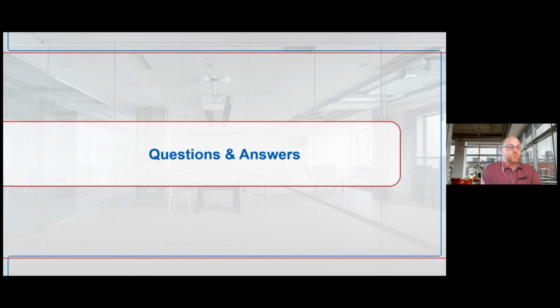Last question that's showing up here is going back again to the horizontal mullion question, of which we've already said that the AHJ has to get involved. And the question is, if there are 3 levels of windows, let's say you're at the wall of a pool, for instance, 30-foot ceiling height, 3 10-foot panes of glass separated by horizontal mullions, will window sprinklers be required at all levels? If you're going to require them anywhere in that assembly, then all 3 levels are going to have to be protected. And as you said, it's going to have to default back to the AHJ accepting the methodology used to protect those 3 levels of windows.